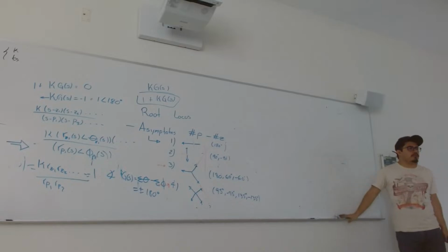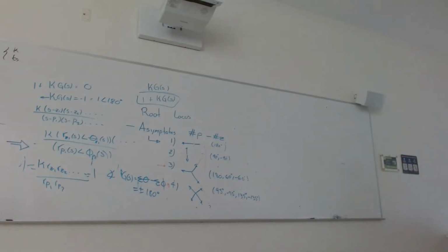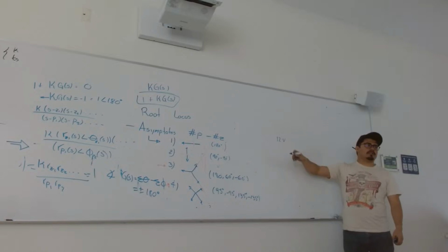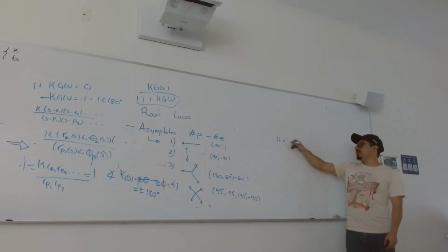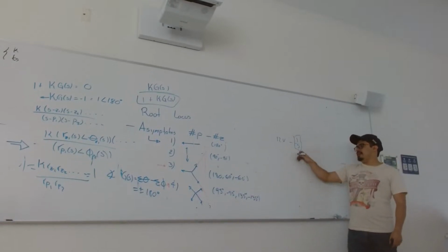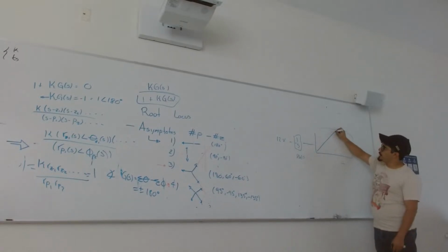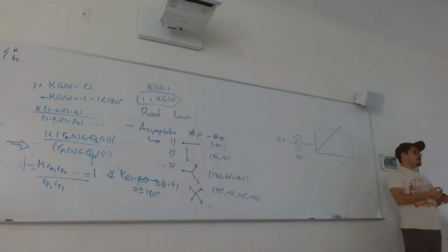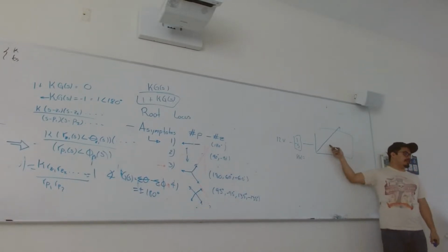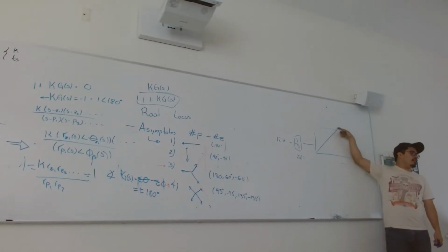Now, give me one of the problems you have. Because eventually you will saturate the system. Imagine you have a line of 12 volts, and you have the integrator with an initial condition of zero volts. It is going to look something like this. As time goes on, if you cannot add energy to the system, how are you going to keep increasing in value?